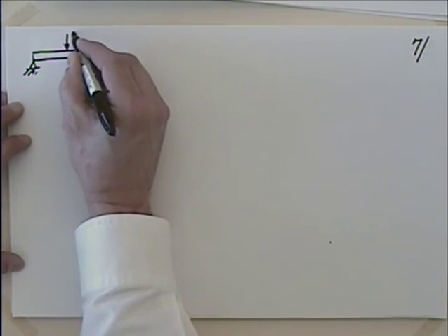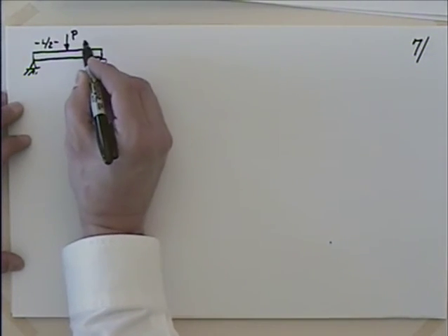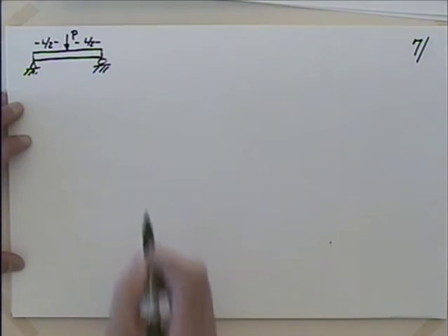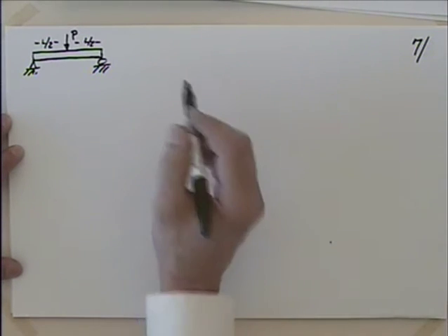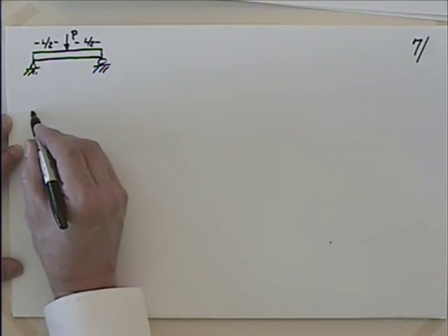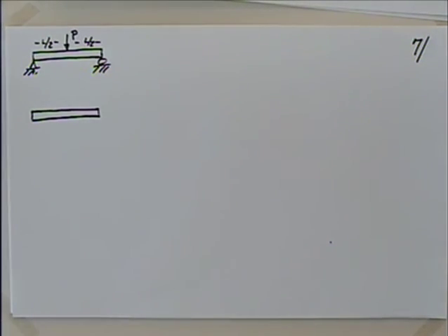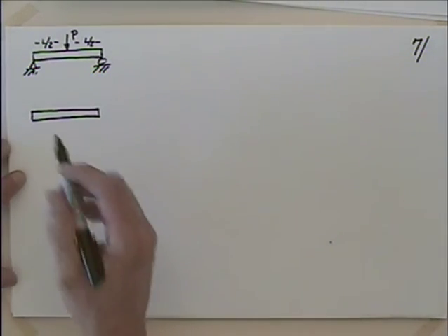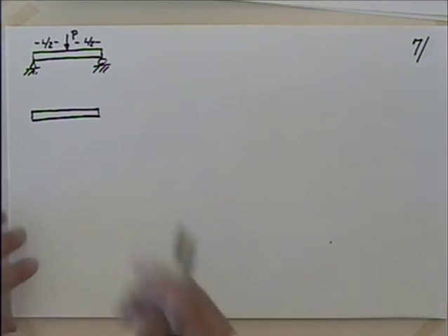I'm going to take a classic example where I have some concentrated load P, located at the center here, L over 2 in that direction and L over 2 in that direction. This comes up quite often, whether you're to throw a plank up over some sawhorses and stand in the middle to paint something, or whether you're going to build an engine hoist, a gantry crane, or something like this. It is a very common problem that comes up, so I'd like to deal with it. The first step is to find the reactions. We'll very soon talk about a shortcut method, if you remember back a few weeks or months ago. But the shortcut method did not allow us to avoid finding the reactions. So finding the reactions is very important.